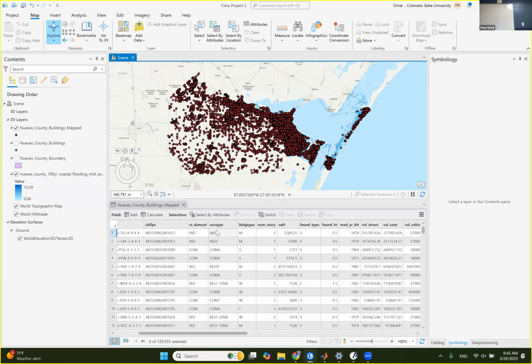So the thing is, I don't want to work with the HAZUS occupancy, I want to work with my occupancy, with my fragility. Because HAZUS does not have a fragility function, they have something called stage damage functions. From my perspective, the stage damage function is not as accurate as ours, or it's a different approach. It's not probabilistic, it's deterministic. It's based on data collected from the field, and some of them are based on engineering judgment. Basically this function is one line. It's like a loss function.